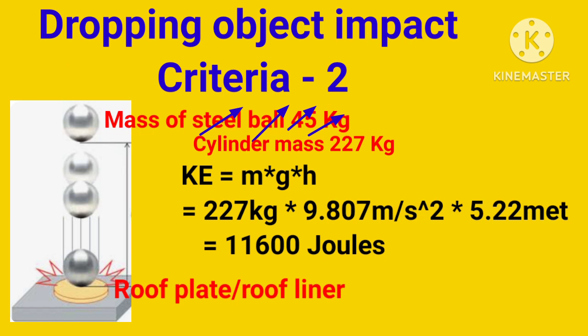For level 1, the impact of the sphere shall be entirely within a 100 mm radius, because you already know that the diameter of the iron ball is 200 to 250 mm, meaning 20 to 25 centimeters, when it is released from a height of 3.1 meters.